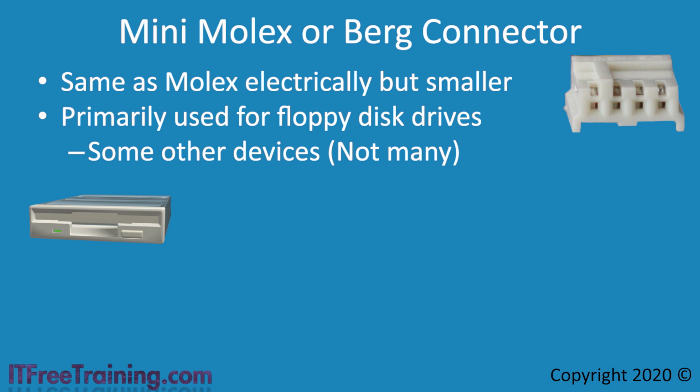Nowadays, the floppy disk drive is obsolete technology. Very rarely, I will use a floppy disk drive to update an old motherboard's BIOS. But having said that, most old motherboards support USB flash drives. I have not had the need to use the Mini Molex connector, I would say, for the last 10 years. For this reason, you will find that some power supplies will no longer include the Mini Molex connector. The main use of the connector is on the back of the floppy disk drive.